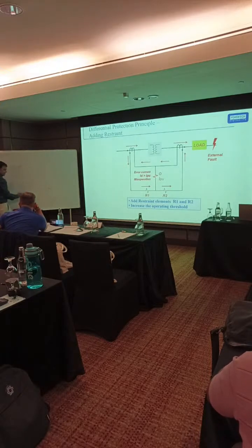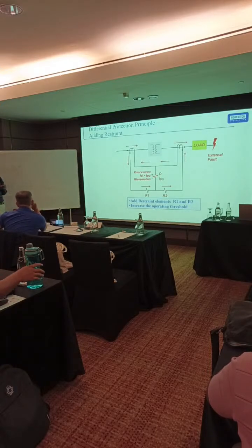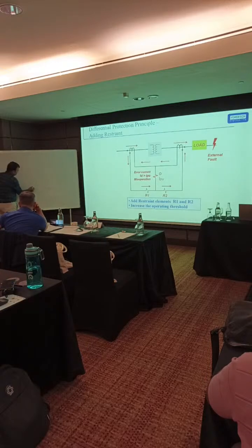You can see this bias current in the measurement of any relay, so you need not calculate it. You just inject the current in both sides, and you can see how much restraint current is there. By formula also you can calculate. So in this case it is 1.9, so it means it is going to slope 3, I think, if it is 1.5. Okay. So slope 3.